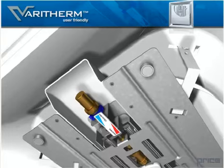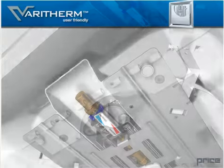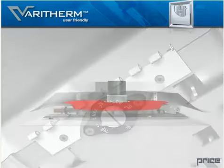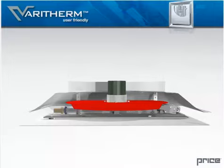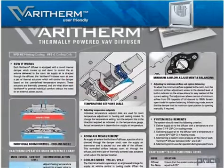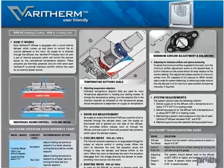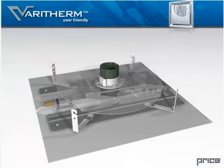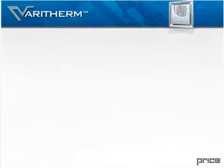Temperature is adjusted with the spin of a dial, and the minimum airflow setting is adjusted with the turn of a screw. The unit is also equipped with a forced open mode to assist in system balancing. All guidelines are simple and easy to follow and are written in a clear format on each unit. Optional security fasteners mechanically lock the core into the back pan, where required by code.